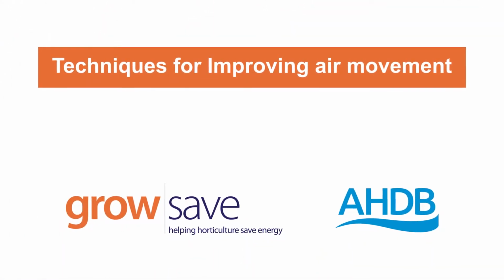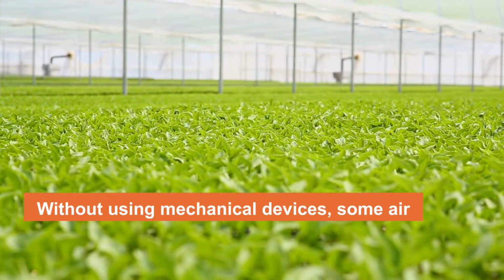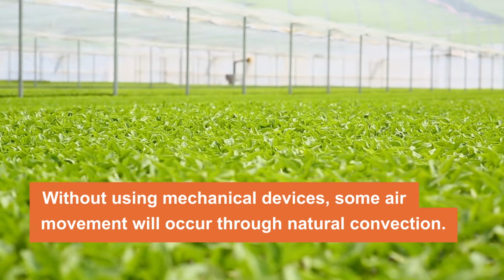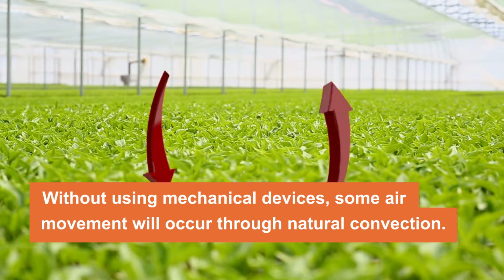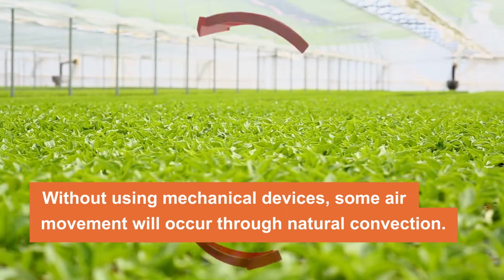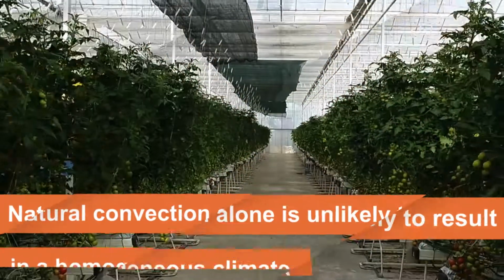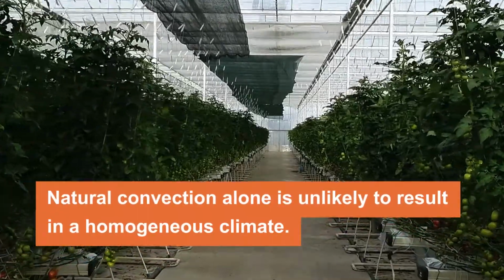Techniques for improving air movement. Without using any mechanical devices, some air movement will occur through natural convection. Warmer air is less dense than cold air, hence warm air rises and cold air sinks, which can lead to vertical temperature gradients in the glasshouse. Relying solely on natural convection to drive air movement is unlikely to result in a homogeneous climate.